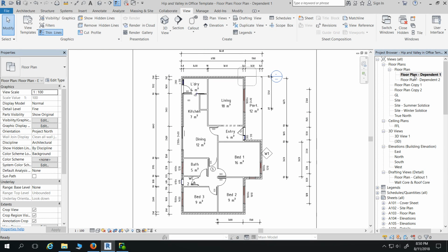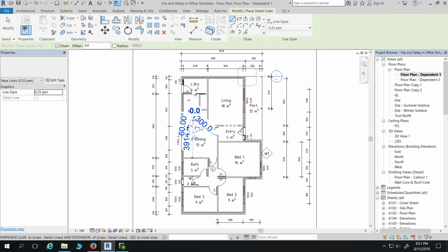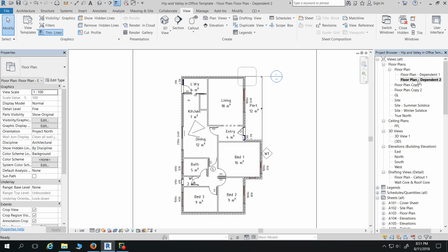So on one sheet, I'll have one that's at scale at 1 to 100 on A3, and then I'll print another one at A2. I'll put it on another A2 sheet, and then when that's printed down to A3, which is 71%, at least it's not to scale. So if they wanted to scale something, they can get the proper one at A3. But the benefit of doing it this way, as Jamie said before, if I add a detail line here, something like that, it will come up in the other view. So it means you're not missing things or you forget to...